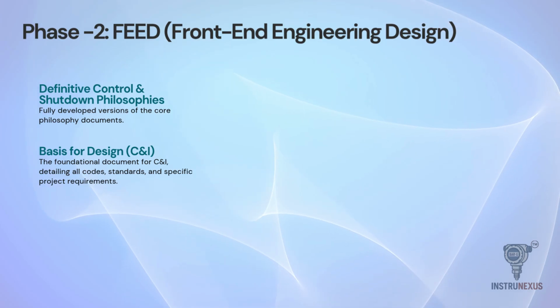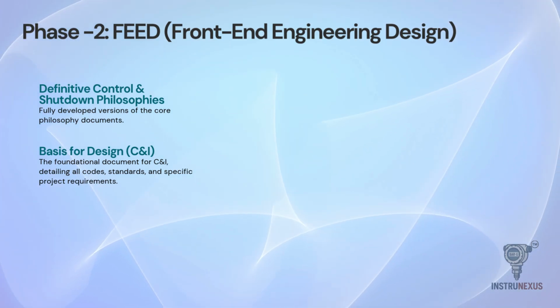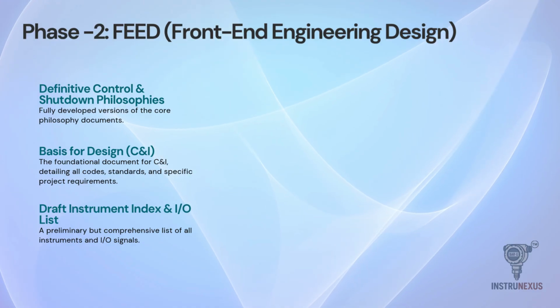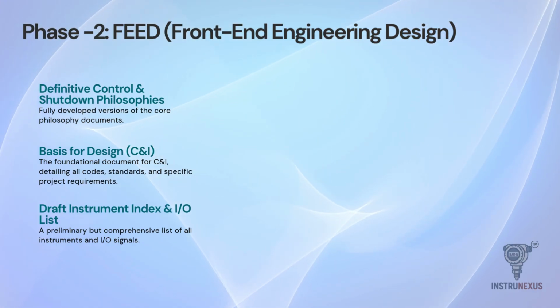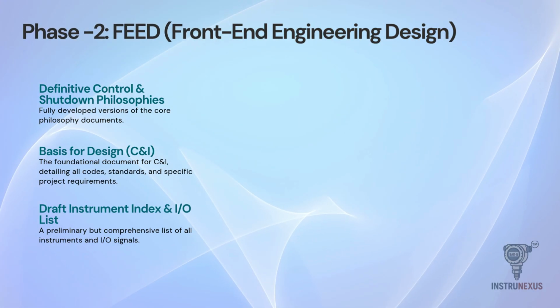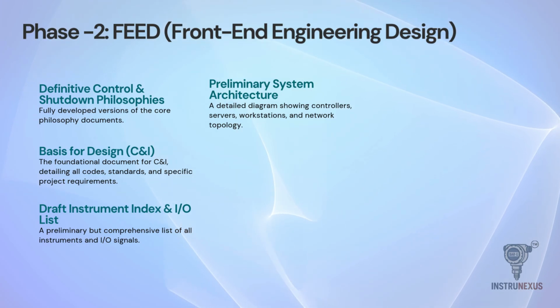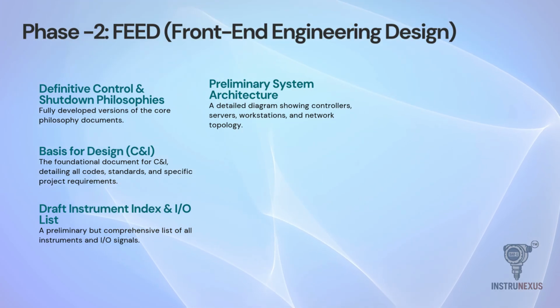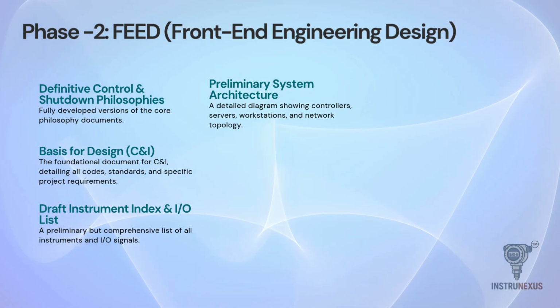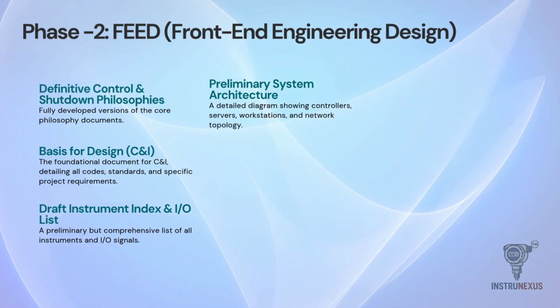of the project. At this stage, we also create a draft instrument index and I/O list, providing a preliminary but comprehensive list of signals. We also refine the preliminary system architecture into a detailed diagram showing controllers, servers, and network topology. This phase sets the rules for everything that follows.